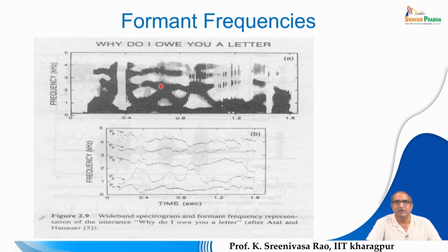It means you see more spectral resolution with respect to the temporal domain, because we are taking a smaller frame duration. The frequencies cannot be resolved vertically, but horizontally you can resolve them.